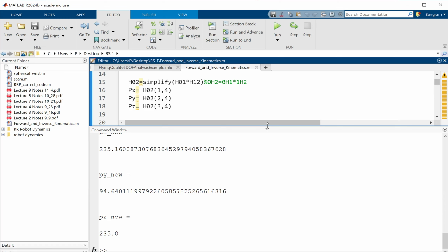You probably have noticed your robot Magician locks at certain angles. If you substitute angles outside the operating region of the robot, it will still give you an answer, but that won't be the correct answer because the actual robot won't be able to reach that forward kinematic solution. Everyone understood this?